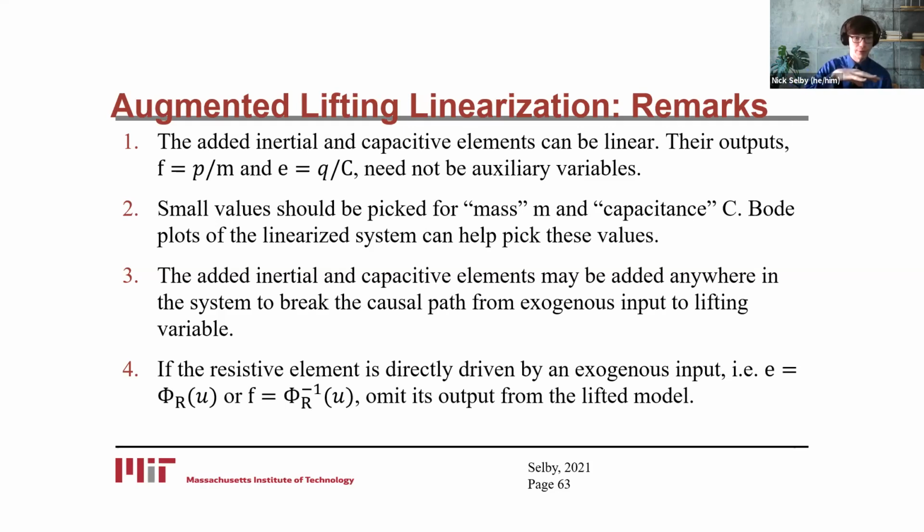And then lastly, remark 4, if the resistive element is directly driven by an exogenous input, right, like E equals phi r of u or F equals phi r inverse of u, it's not actually affecting the state dynamics, right? Like these are not functions of state at all. So you can just omit this output from the lifted model altogether.